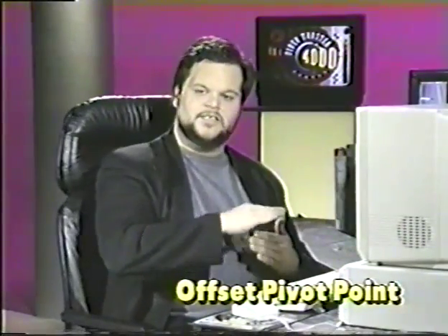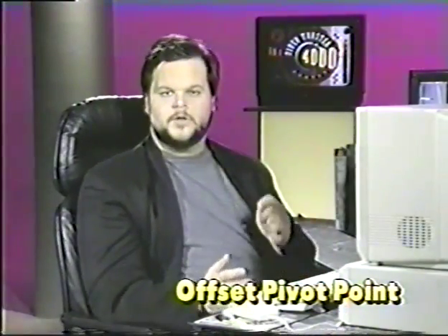Now one thing that we're going to do here is I want to offset the pivot point. I've got it centered right now. But if I want to make it look as though this text is moving along the curved path, it's really pretty easy to do. We're going to offset the pivot point. Rather than keep it in the middle of the object, we're going to have the object set away from it. This way, since it's rotating around the pivot point, it'll look like it's moving around a curved path.